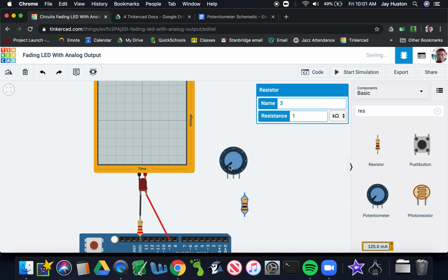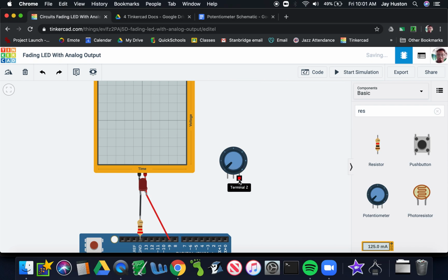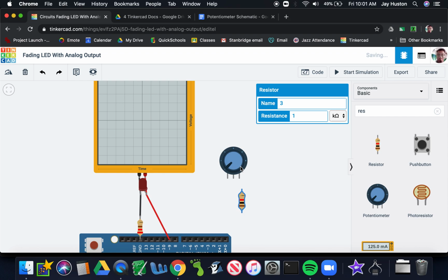So when the knob is way over to the right, there is no resistor. The resistor is gone because energy comes in this pin and goes straight into the wiper and straight out, and there'd be no resistance. So that'd be full volume. And as the wiper gets turned, the wiper being this knob right here, right now the wiper is at the lowest setting. As the wiper goes from the highest setting to the lowest setting, what you're really doing is changing this resistance from, let's say, 1 to 10 to 100 to 1,000, depending on what kind of potentiometer you have.